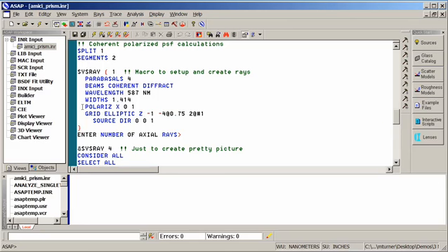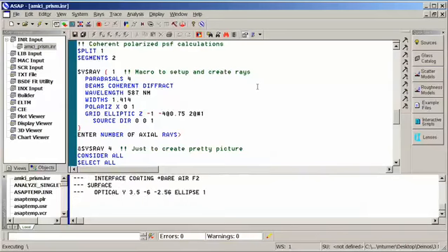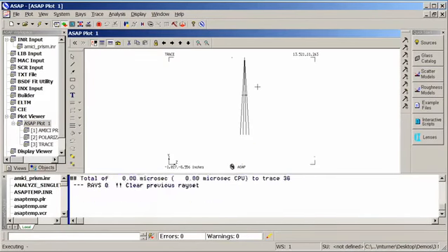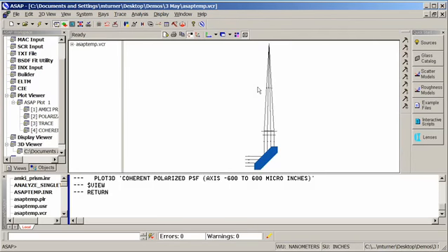So what we're going to do is see what happens to the coherent wavefront and the polarization state as we propagate the light through the system. And let's just take a look at the results. In this particular case, we're actually going to propagate the wavefront in steps. First, we're going to propagate the wavefront simply through the prism and take a look at the polarization state.